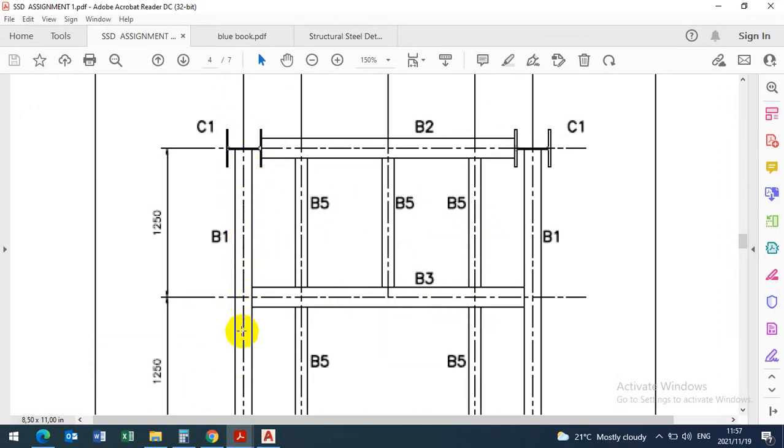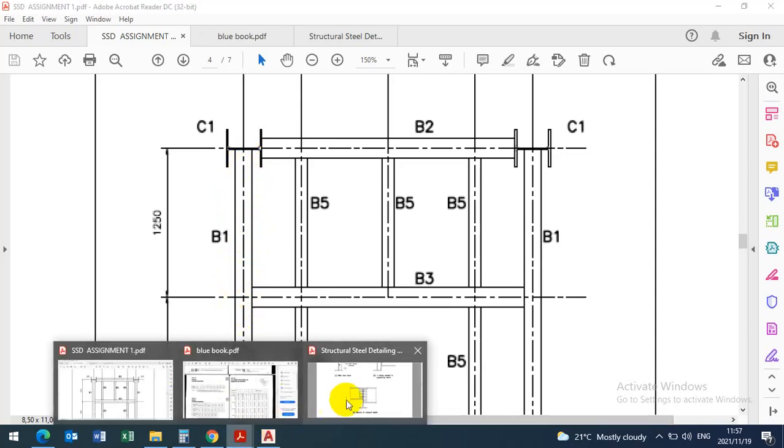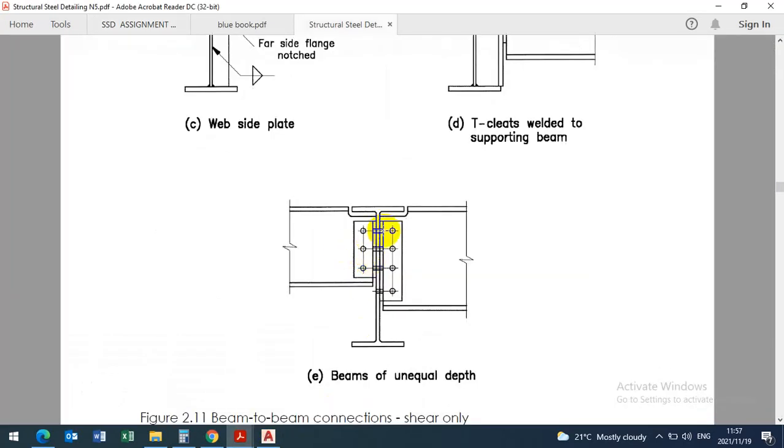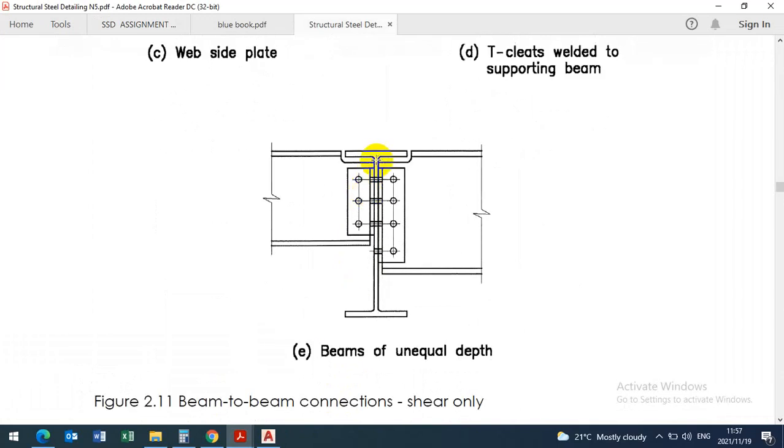Because we are saying that this center line is the web and the flange is the top. So it's standing the same way you see this one here, except that we won't have this side here, but we'll have this I beam. But when they want a detail of the beam, we need to show the length. So we are not going to draw like this. We need to project from these corners going up, or coming down. But we are looking from the top view. From the top, what do we see? We won't need the detail of this beam 3.